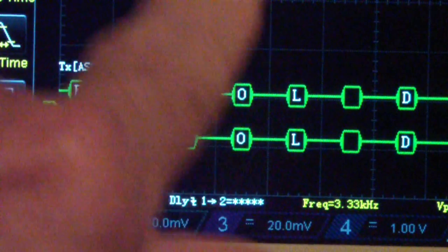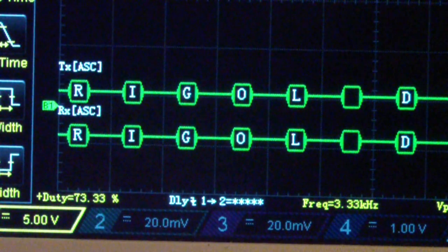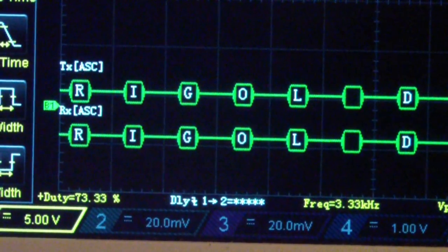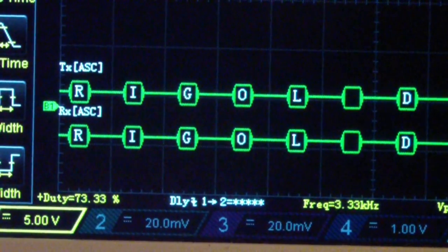You can do all of this in a table and some other things that I'm not going to go into at this point, because as far as I'm concerned, the fact that the Rigol allows full ASCII decode and the Siglent does not means that if you're going to use a scope in an RS-232 decode, then I would say go with the Rigol. I think Siglent needs to rethink their decode options and add an ASCII decode. So that sort of concludes the comparison between these two.